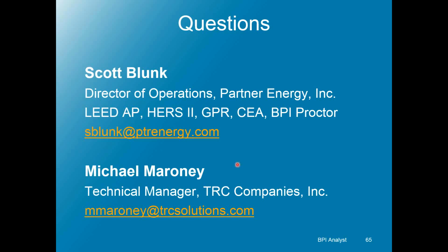I've done this kind of study on multifamily buildings before and been able to dramatically reduce the size and therefore the expense of the water heating system going in. But the smaller the system that goes in, the less standby loss you're going to have also. So not only do you reduce the cost going in, but you're going to reduce the operating expenses. But it's harder to do on residential because there's not very many options there.